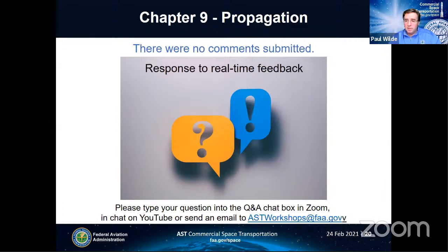And our past experience suggests that by far the best way to do an analysis involving a large set of winds is not to start with a statistical description, but instead to start with a library of actual sampled conditions. And those types of things are available these days through various weather services, including, of course, NOAA and the Air Force.